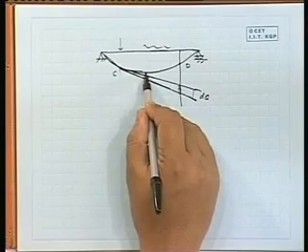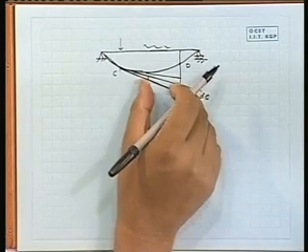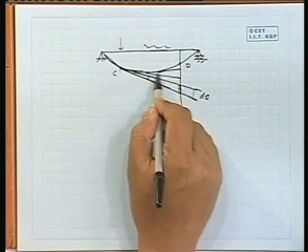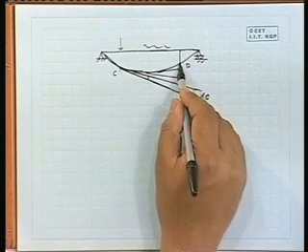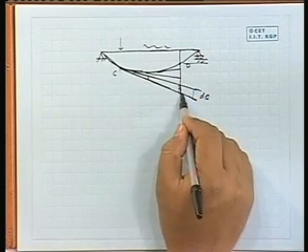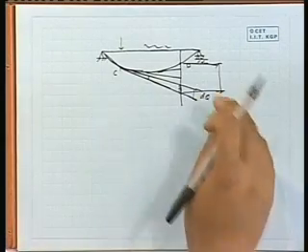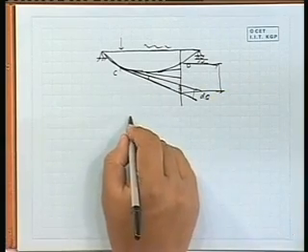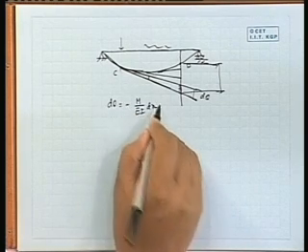If we take another point and draw it, there will be another d theta, so you have to multiply by the corresponding distance. If you take another tangent, it is d theta multiplied by this one. So if you go on taking small values, this part will be your d theta, which you have already written as minus M by EI dx.